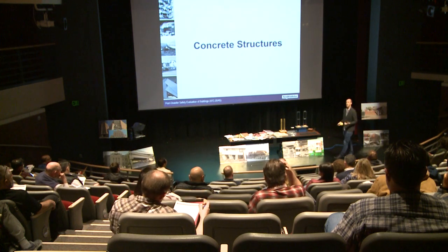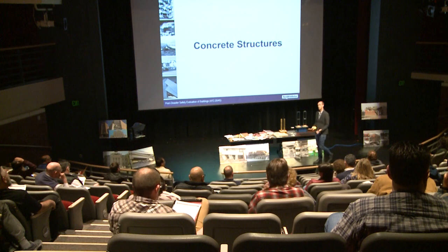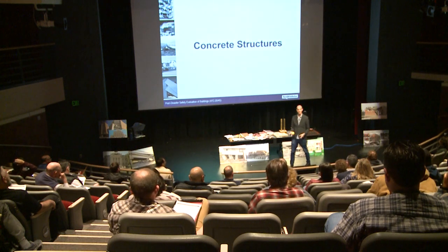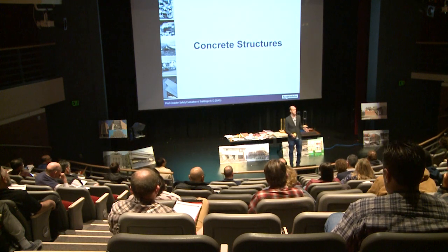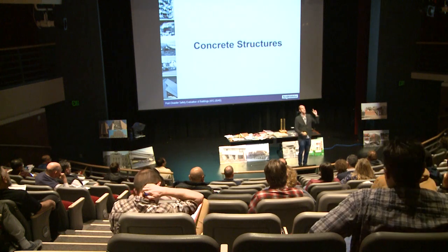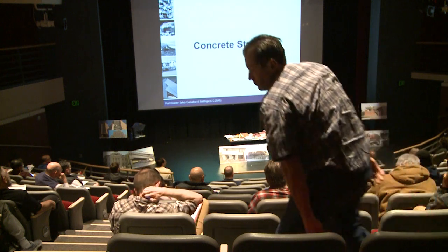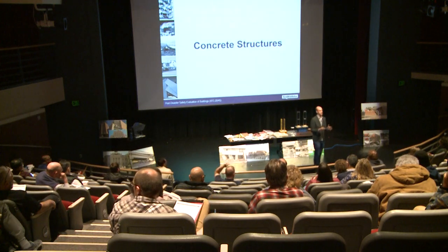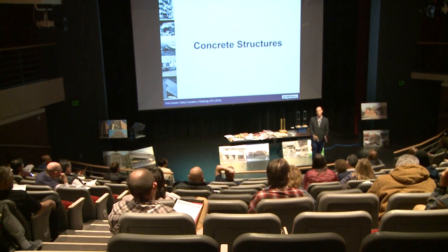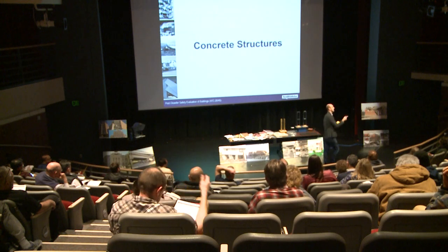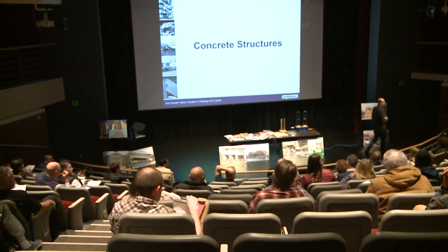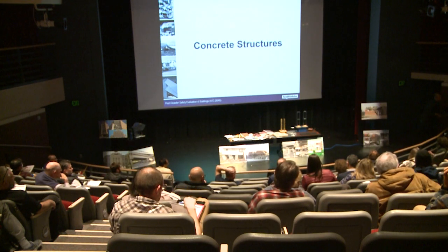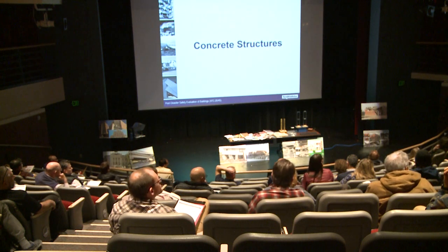So you show up on a multi-story residential building, where are all the residents going to tell you to come look? It's always the people on the top floor units saying, you've got to come up here, look at the cracks in my drywall on my top story unit. Where should you start your interior assessment? At the bottom.